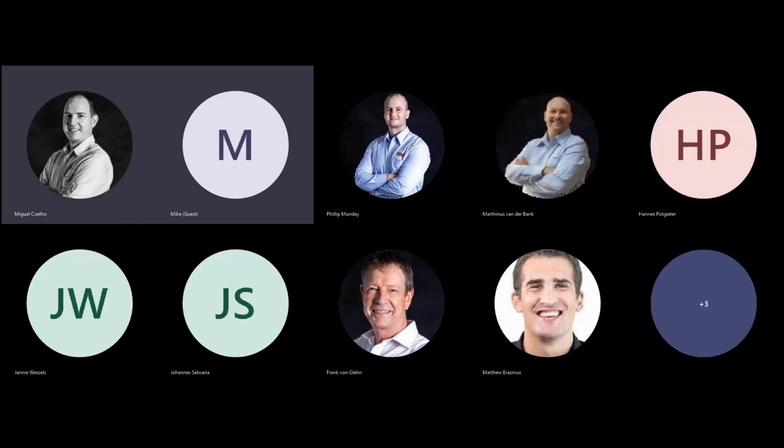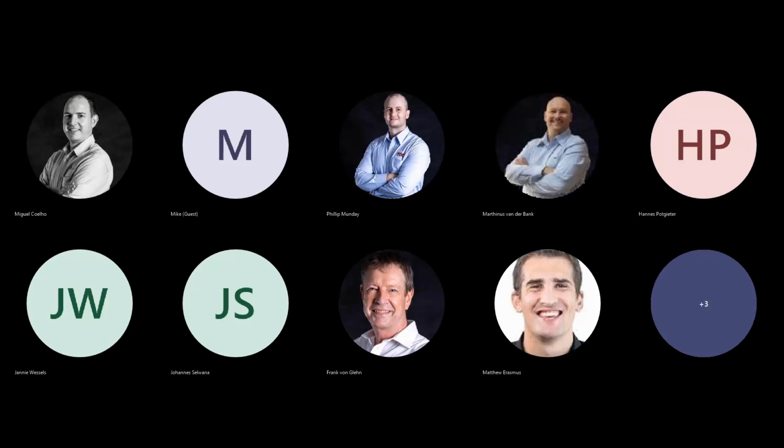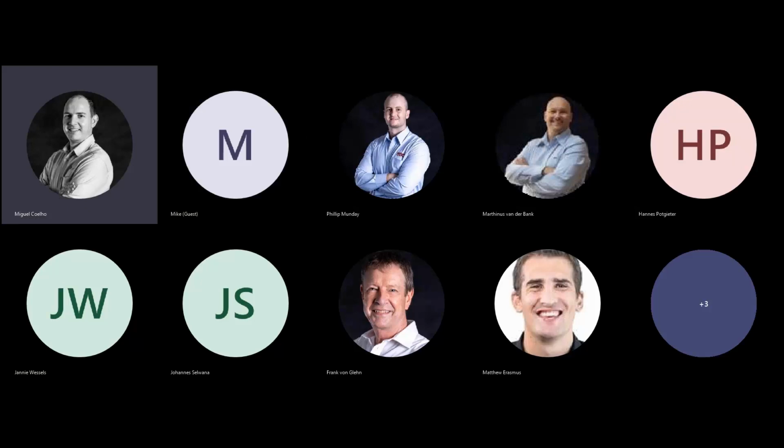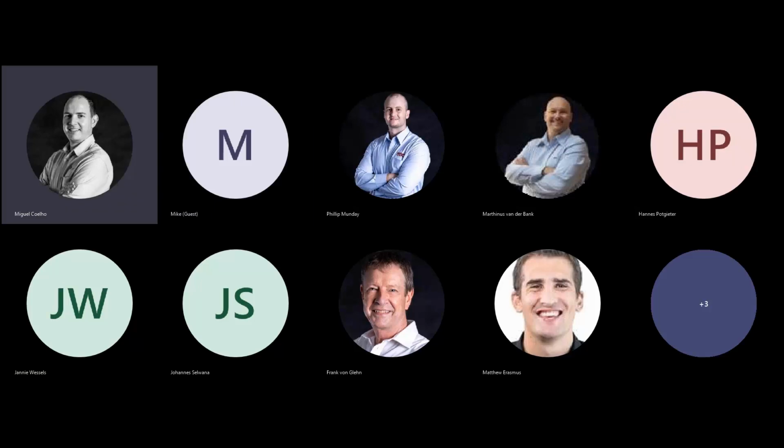Okay, well, I appreciate that. Thanks. Mike, what you can also do is typically the guys have a blank VUMA network file with the library fans that they always use. And then from a new VUMA file, you can import fans that are in a pre-existing model so that you don't have to always re-import. So you'll import that Kaufman contra-rotating fan once, and you'll just keep importing it into your other models. Putting it online globally just makes it available to anyone who uses VUMA, which is also of great benefit.